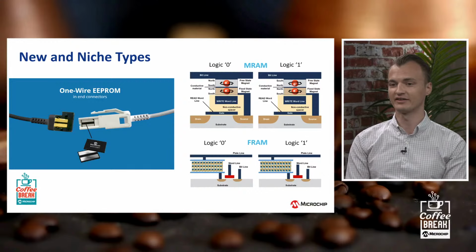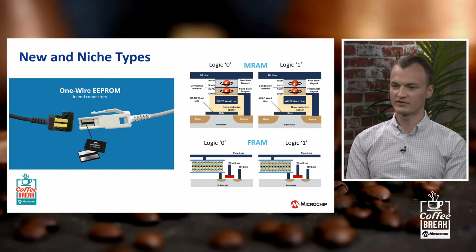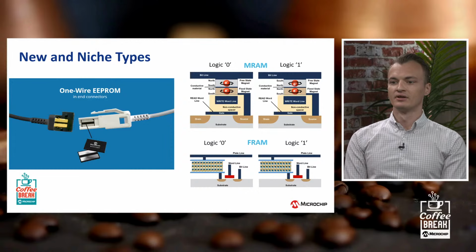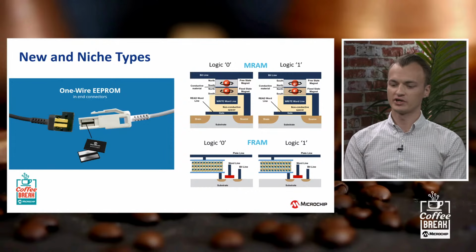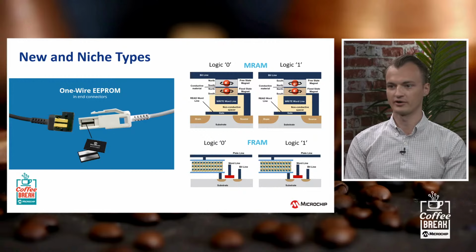And the catch is it does have endurance, although the number's pretty high. It's usually about 1 trillion cycles. However, the reading it does wear it out, so you do have to take that into consideration. It is also expensive to manufacture, so it's kind of expensive to buy it. So it's really only good in situations where you cannot afford to lose data at any point, you don't have time to transfer that data over to another memory, and you need extremely fast erase and write times. So that's what it gives you.